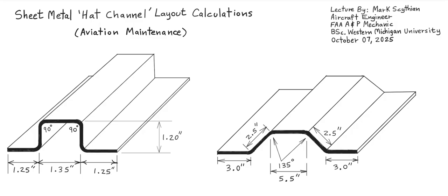So making your first bends, starting with the 90-degree hat channel on the left, we'll have to start at the upper tier as the first bend, and then the other side of the upper tier, either or side, followed by the outboard sides, second to last. Because if you were to start bending the outboard sides, then you could not fit the sheet metal piece into the sheet metal brake, and then you'll have to redo it.